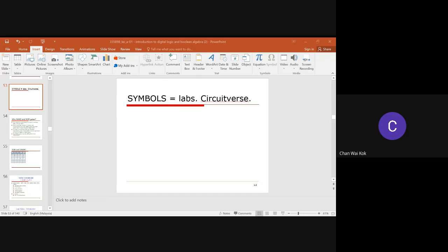No, not too complicated. Okay, let's say you have a chip, you have a function, right? Some function 1, you might use 3 AND and 2 OR and 1 NOT. Then you have a function 2, you might use 10 AND and 1 NOT. Then you have function 3, you might use 10 OR and 1 AND, like that. How are you going to optimize the circuit? 3 different components in your chip. So what you're going to do? In your chip, you just have NOR gate, NAND gate only.